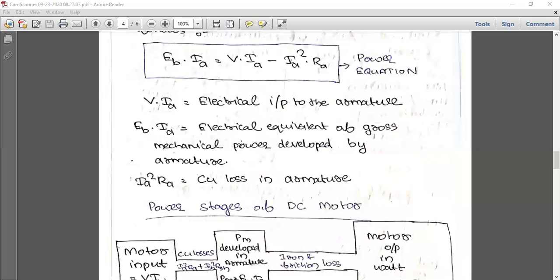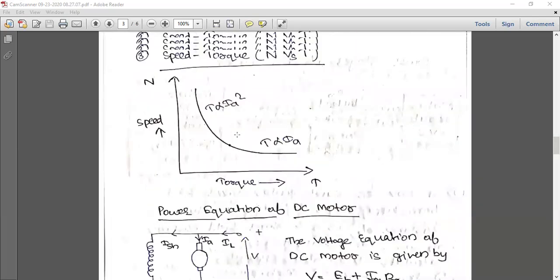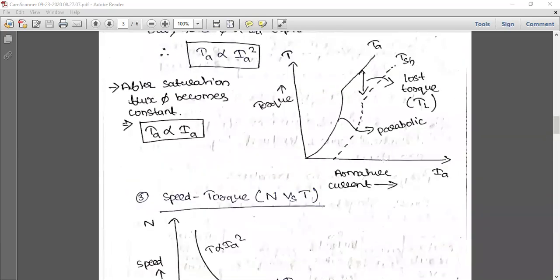This explanation is there in this figure. That's why I didn't explain it to you at that time. So this is actually a loss torque due to iron and friction losses, and the output machinery we connect to the shaft, and TSH, the shaft torque, is the torque available.